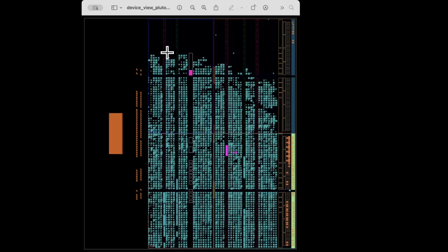So, like I said, when you have to balance one to the other, you have to decide what functions go into software versus the FPGA. Here's the FPGA as of today, pretty darn full, but we're going to go ahead and try to fit all this stuff in hardware. If it can't fit in hardware, it already exists in software. We already know how to do it and we're good. When we go to a bigger chip or a custom board, we'll put it back into hardware. So this gives us a lot of flexibility and it keeps the spirit of Matthew's modem module approach fully alive. So we're able to handle both cases.